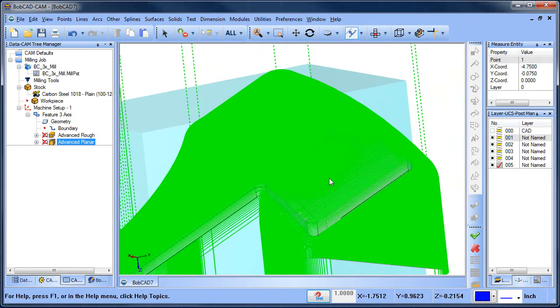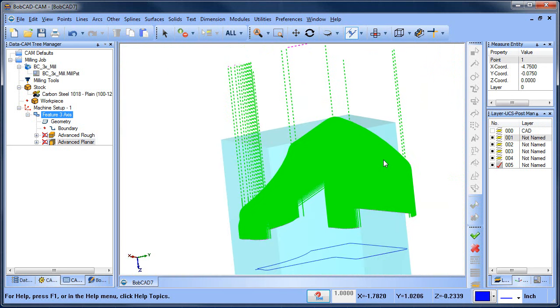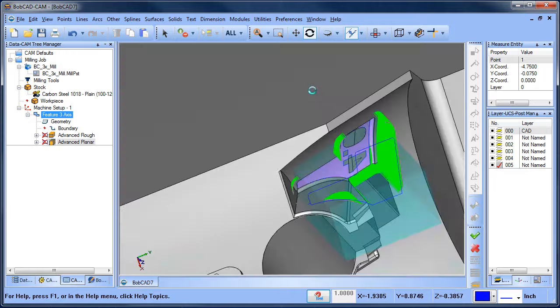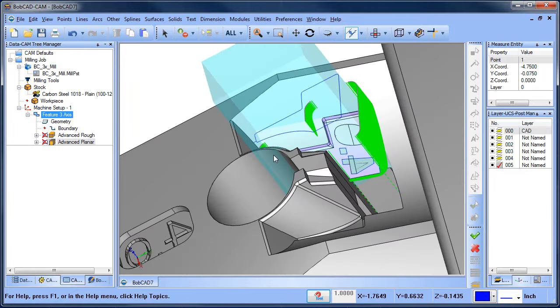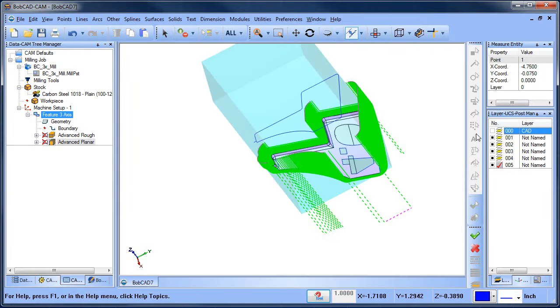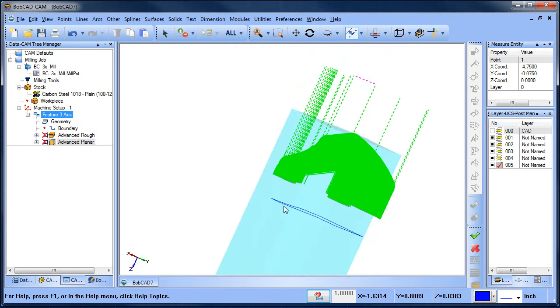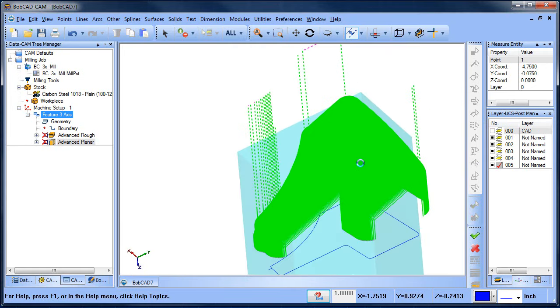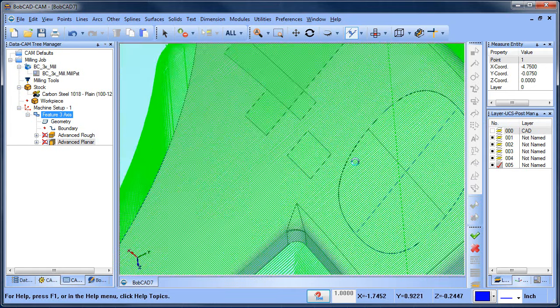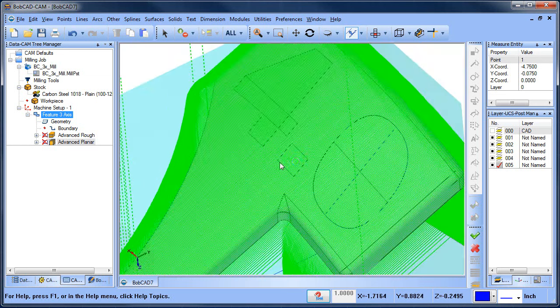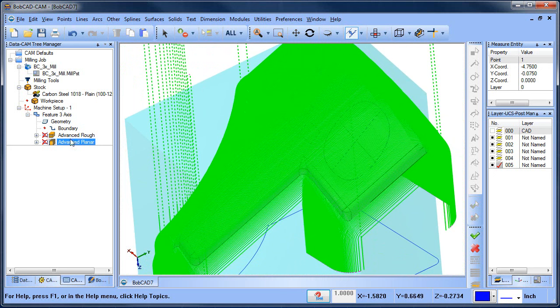Now, some of the other options that we have. So this would be like a Mill Pro type scenario. Again, as far as for the Electrode design, really we just took the surface where it was, we isolated it, we created a boundary for our wire blank, we filled in some surfaces, and we started laying down toolpaths. So we didn't have a whole bunch to do there. But we do have other cutting strategies that are beneficial.